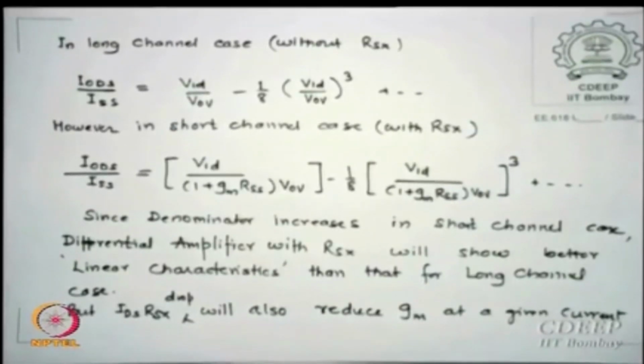That is true. See, what is design? If you achieve something, you lose something. But do you get the point? This is something many people did not realize, that in a short channel device everything goes wrong, but here is something that can do good: your linearity may improve. And that is why, when I start a new design, I should look into which technology I am using and what linearity improvement I got through it. That has an advantage on output swings, because some applications may benefit from that.